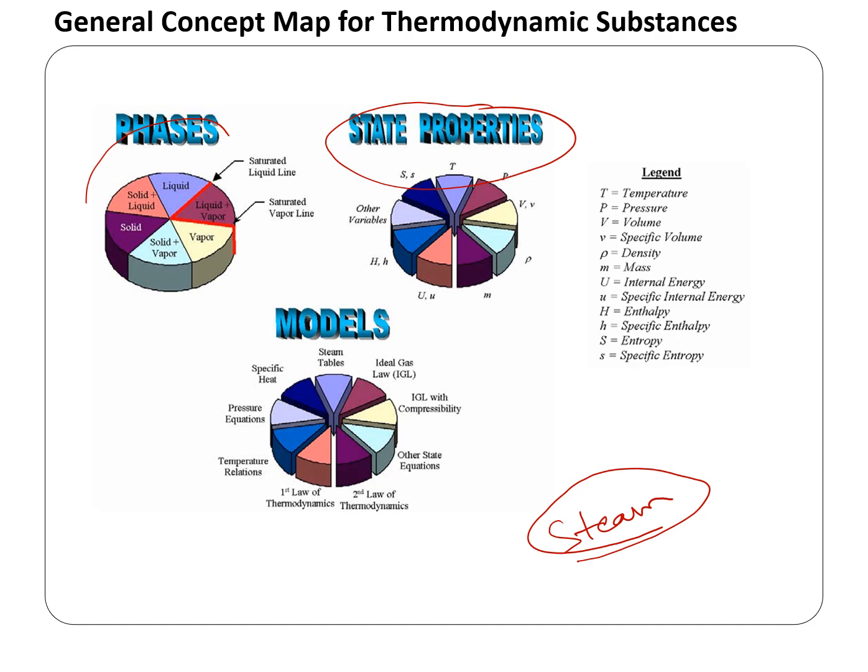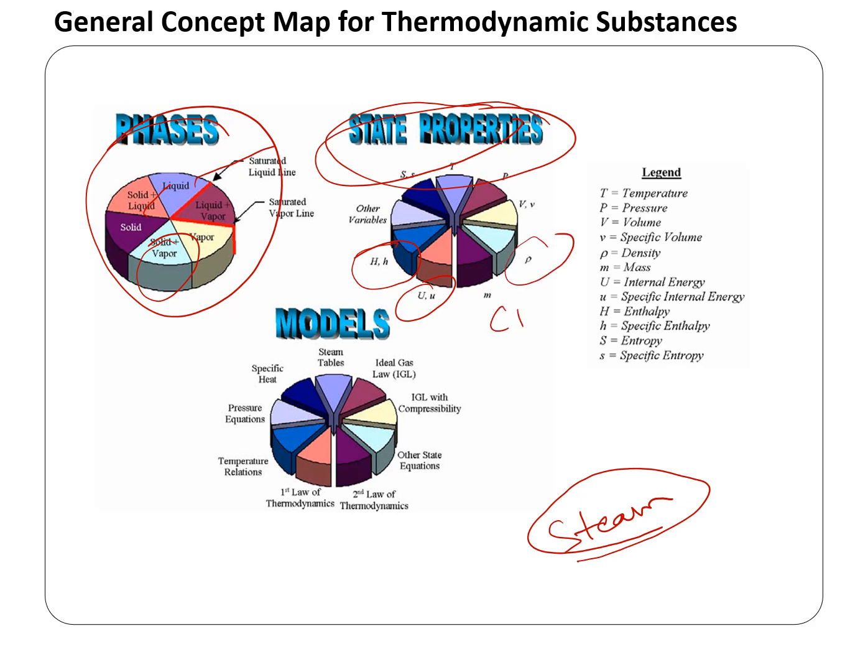So you need to figure out what phases are present, sometimes liquid, sometimes solid and liquid. Based on that, you try to find the state property. It could be pressure, temperature, internal energy, enthalpy, density, even CP and CV. So try to figure out the property at a given pressure and temperature. That's finding the property from the appendix, mostly through the property table.